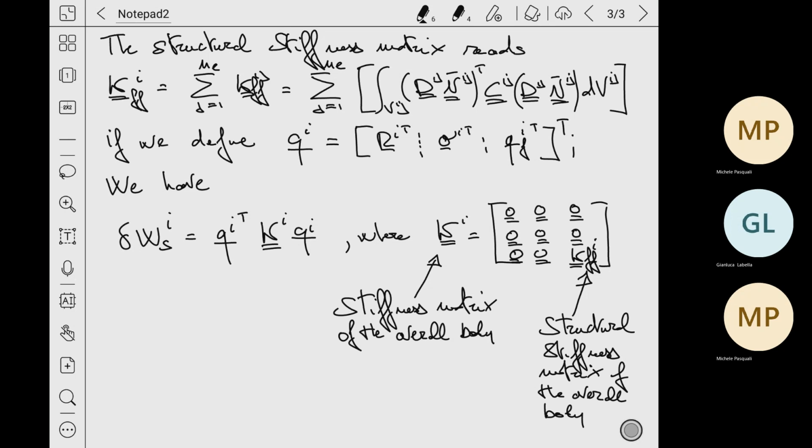On the other hand, in our case, in the floating frame formulation, you adopt a local point of view, and then you report it eventually to the absolute frame. You do not see, in the hypothesis of small deformation that we have always made, any change of mutual orientation between the forces and the body. And that's why you have a constant matrix.